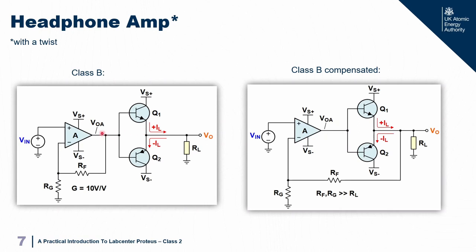The problem with that is if you're listening to really quiet audio, for example in headphones, or you've got tiny little earbuds that only need a handful of millivolts to run, you might be within that dead zone, and therefore they don't even produce anything. There's no output. If you go beyond that, you get this horrendous thing called crossover distortion. I've got a slide to show you what that looks like. How do we overcome that?